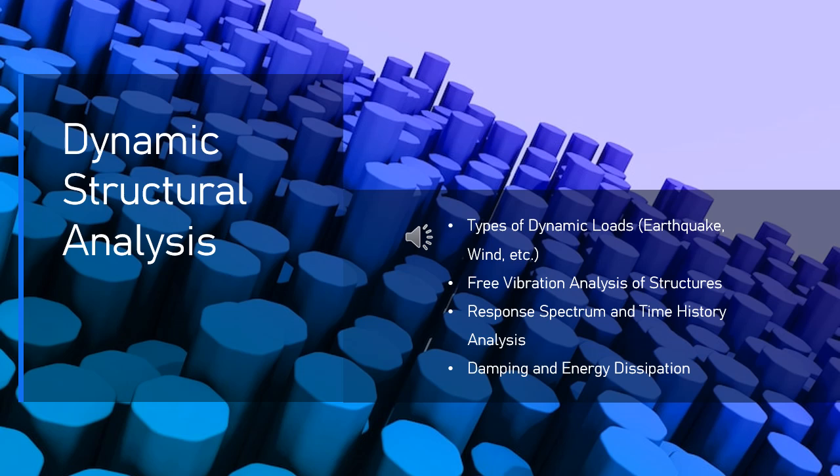How does time history analysis work? Step 1. Input dynamic load. The dynamic load, e.g., seismic ground motion, wind load, is represented as a time history. In seismic analysis, this is usually a set of acceleration time histories recorded during an earthquake.